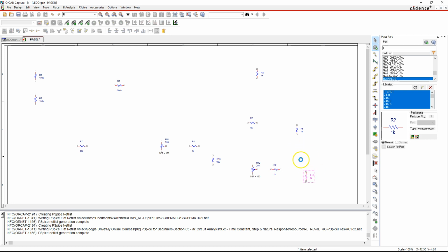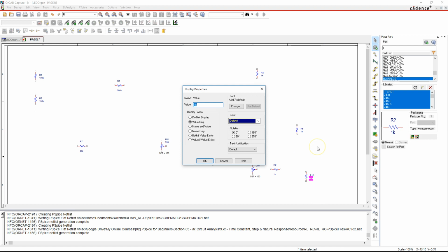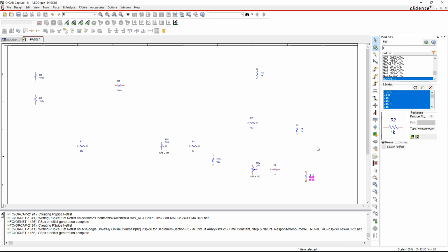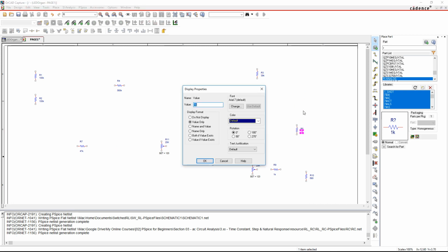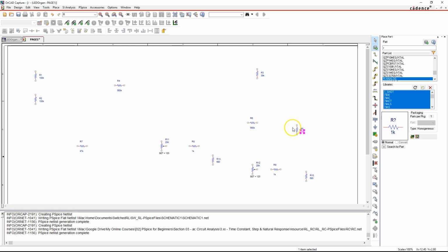And then this resistor here also needs to be 680, similar to this resistor. See if there's anything else I might be missing. I'll change this 1K to 560 kilo ohms. And then this resistor up here, I'll make it 39 kilo ohms. I'll also give this resistor a 39 kilo ohm value.